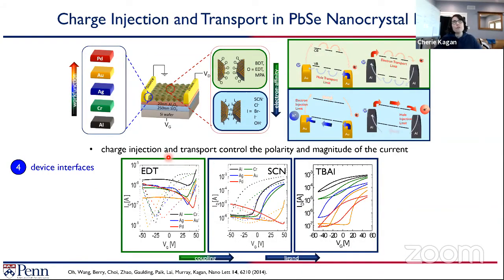I also wanted just to share with you the idea that the electrodes and ligands can be very influential on charge transport. So this is an example where we looked at the lead chalcogenide materials. We looked at many of the different ligand chemistries that are explored by our community. These could be short organic ligands or these compact inorganic ligands. I have to admit, it really highlights the idea that less is more from a standpoint of charge transport. Where you can see if we expose ethanedithiol, regardless of what ligand we use, the resistance to transport in the channel is so high that they all look the same, and the current levels are very small. And so it's really transport is limited by interparticle charge transport in these materials.